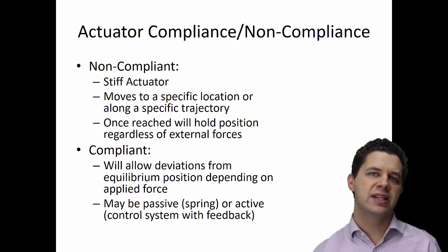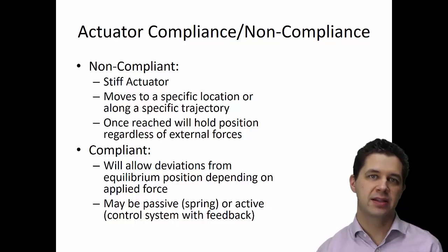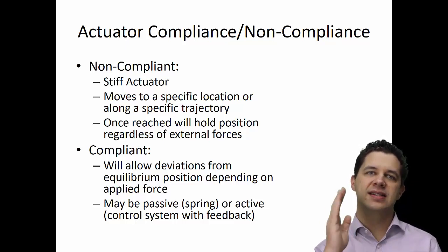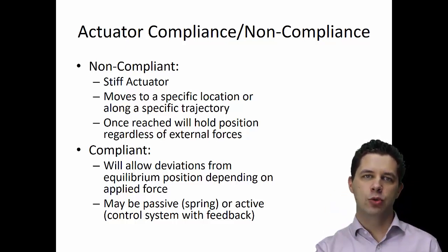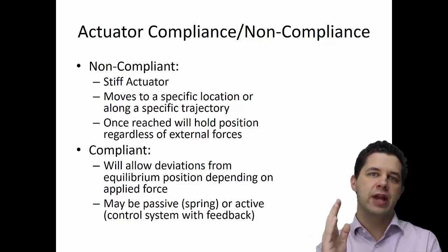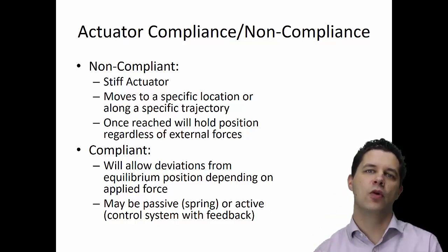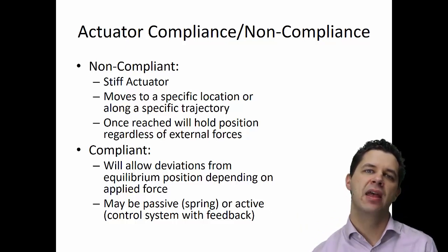One other interesting characteristic about actuators is their compliance. Essentially we've got compliant actuators and non-compliant actuators, or actuator mechanisms, we should say. The non-compliant ones are essentially stiff actuators, where once you program it to a position, it will move to that position, or along the trajectory, and it will hold that position regardless of the external force that we apply to it. So we push it, it's not going to move and it will resist our force.